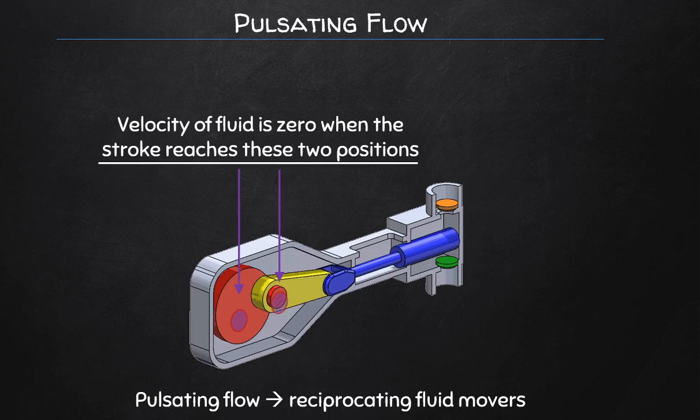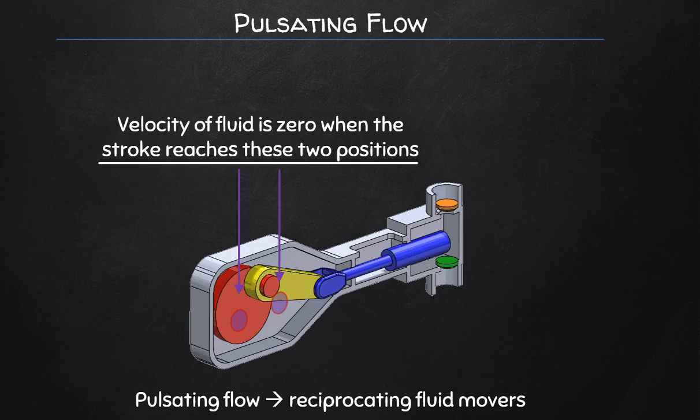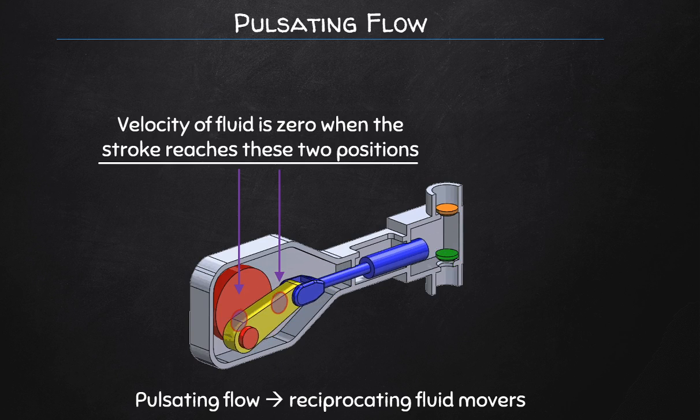Now the cause of the dynamics are obviously due to the velocity becoming zero at certain intervals of the stroke action. So watch the stroke action and think to yourself where the velocity is going to equal zero. Okay, so I've shown it here at the purple points. Just look at the purple circles and then look what happens at the piston. The piston stops and has to reverse, and then it goes and it stops and it reverses. Okay, so this is the cause of these dynamics.